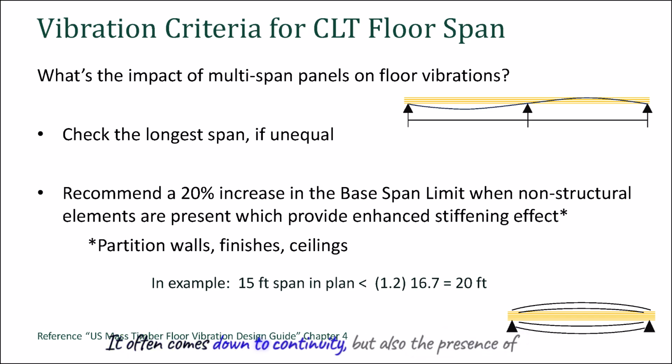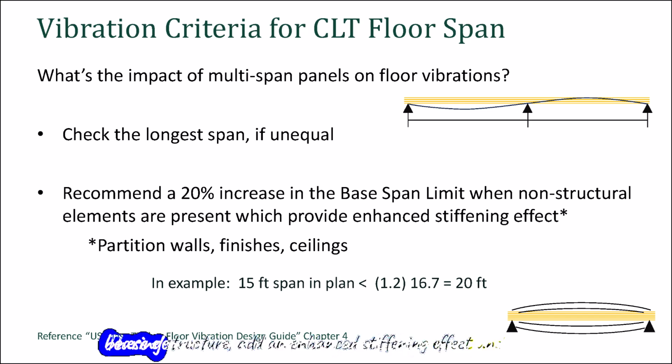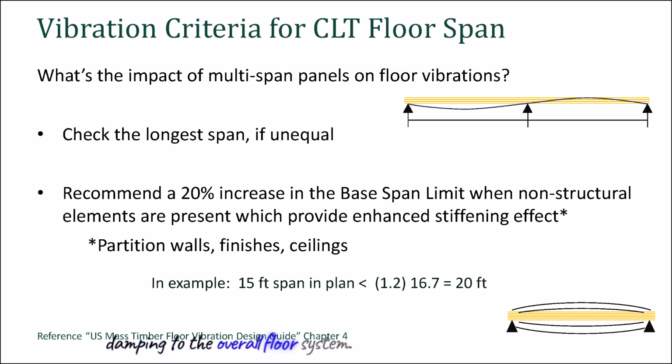Why? It often comes down to continuity, but also the presence of non-structural elements. Things like partition walls sitting on the floor, heavy floor finishes, or even rigidly attached ceilings. Things that aren't part of the main structure but add stiffness or mass. Exactly. These elements, even though they aren't the primary load-bearing structure, add an enhanced stiffening effect and damping to the overall floor system. This really helps dampen vibrations.